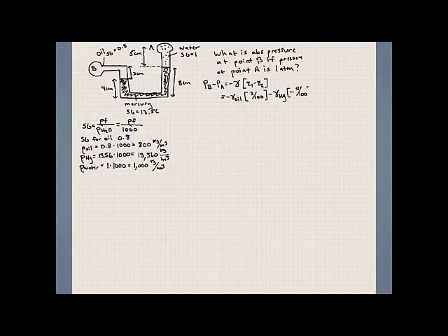So I'm going to write 4/100. And the last fluid that we're dealing with is water. So I'm going to go ahead and write minus gamma of water, H2O. Let's determine if it's positive or negative. It is starting out at the interface between the mercury and the water. So the first point is below the second point, which is the last point, right in the middle of point A. Because Z1 is below Z2, we will say this is a negative 5/100. Okay.